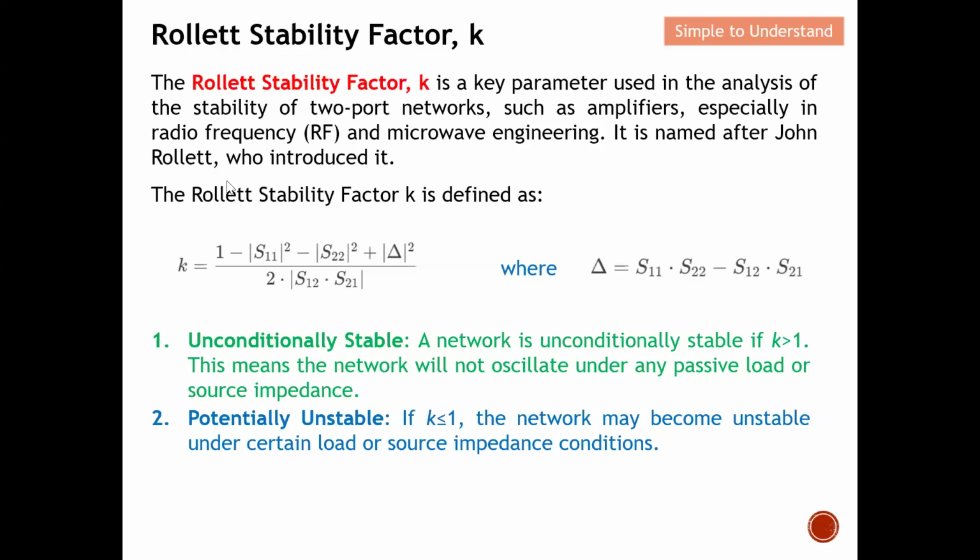What is this equation? This is the equation for the Rollett Stability Factor. I will have another video, part 15 of the series discussion, to show you an example of how we can compute this Rollett Stability Factor. But at this moment, let's take this equation. I just want to highlight a few things. You see that this is what we call the magnitude. We forget about the imaginary number. We only focus on the magnitude.